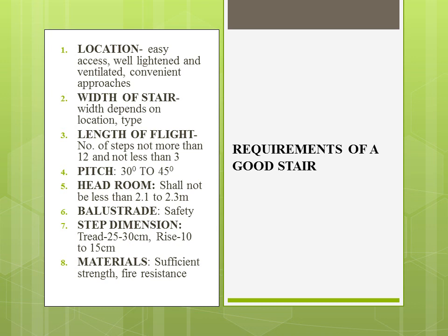The width of stair should be such that it should not overcrowd, and the width depends upon the location of the stair and the type of building. The length of flight should be such that number of steps should not be more than 12 and should not be less than 3. The pitch should be maintained between 30 degree to 45 degree.